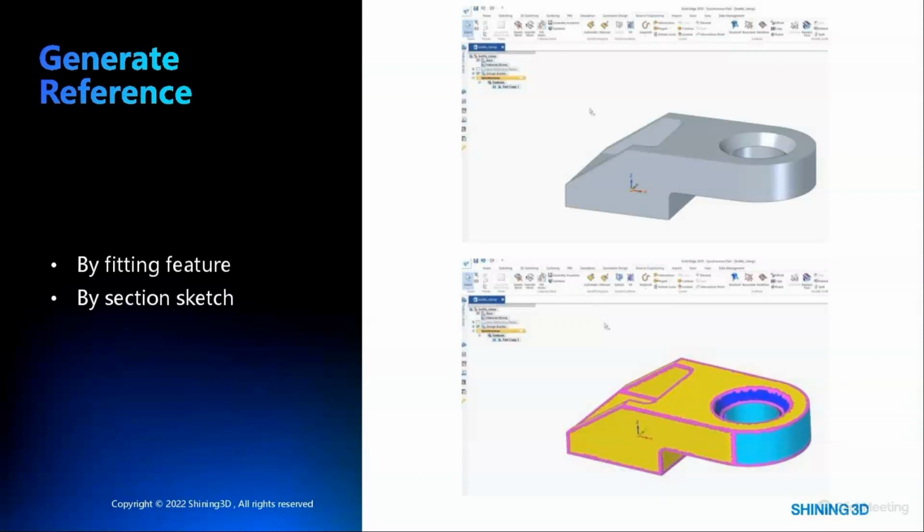And like I said, the feature you fitted, it's not perfectly parallel or whatever. There's no restriction to the direction or to the shape. It's purely based on the scan data and based on the area you selected. However, it doesn't mean there's nothing you can do. In the future, you can still restrict them because it's a CAD software, so there's always a way to restrict your surfaces.